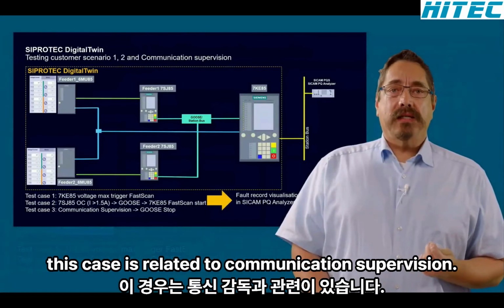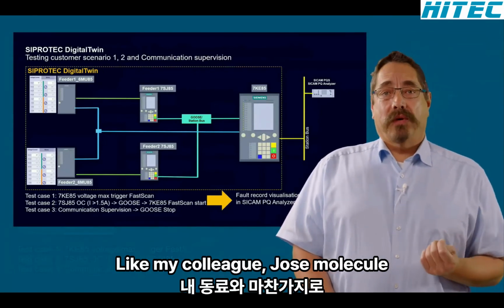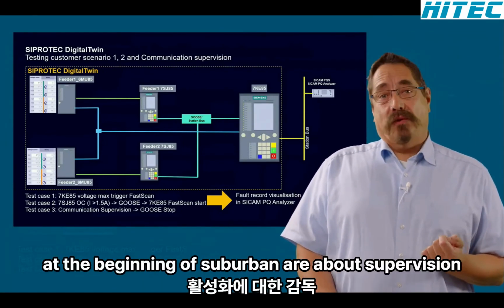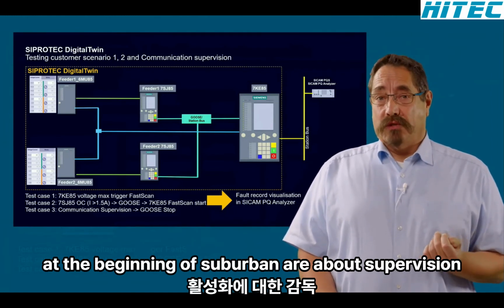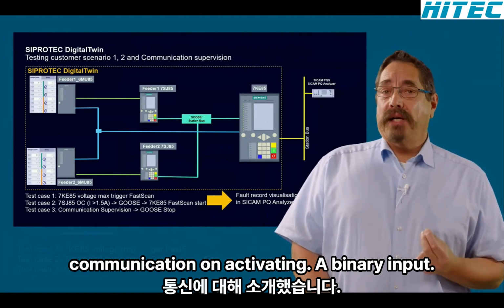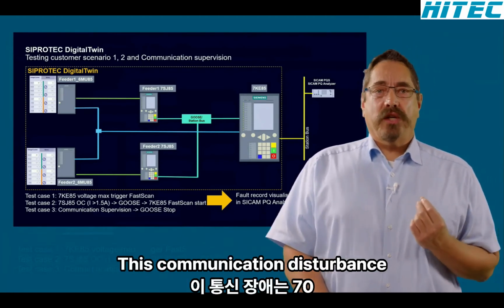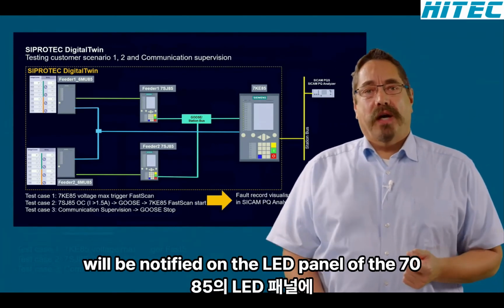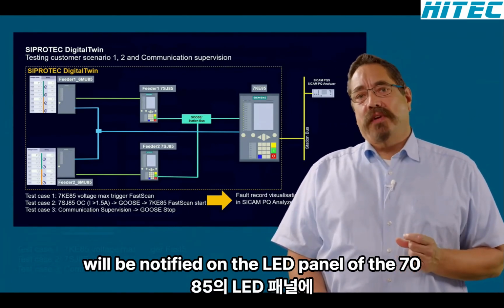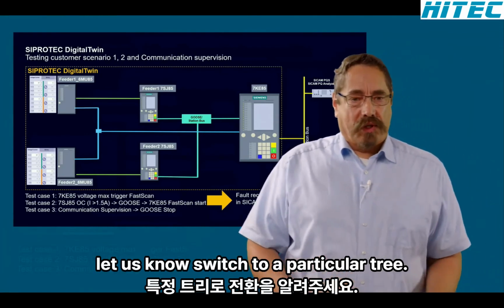The last test case is related to communication supervision, like my colleague Jose Malagón introduced to you at the beginning of the webinar. I will block the GOOSE communication by activating a binary input on the 7SJ85. That communication disturbance will be notified on the LED panel of the 7KE85. All right, let us now switch to the digital twin.